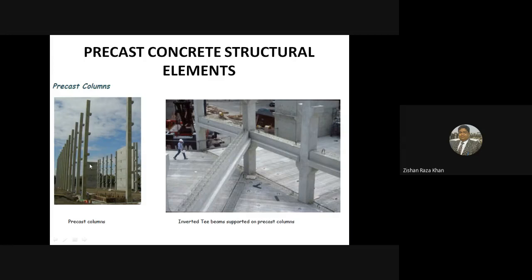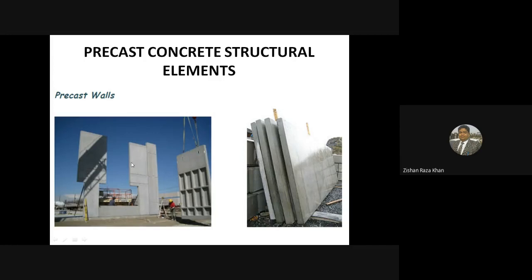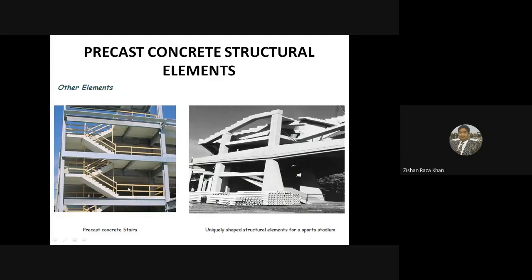See, these are precast columns, and you can see the notches are there to install the beam. These are columns having corbels, and you just put the beam piece and fix it. Okay, so you can have the frame. See the precast wall section. These are panels which are transported to the site. Just put them together, and you can build this type of structure using an entirely precast system, entire precast roof. Stairs can also be transported.